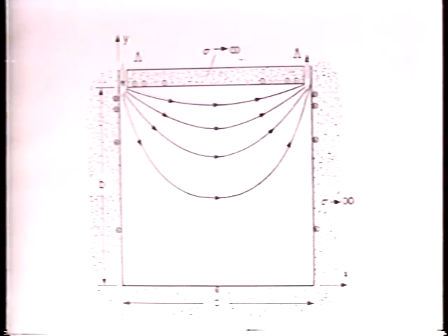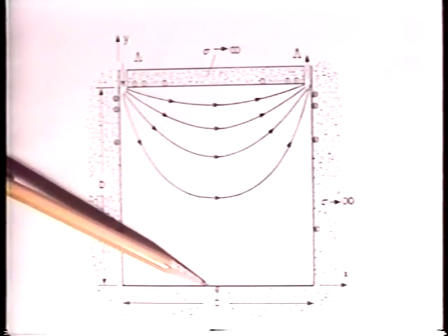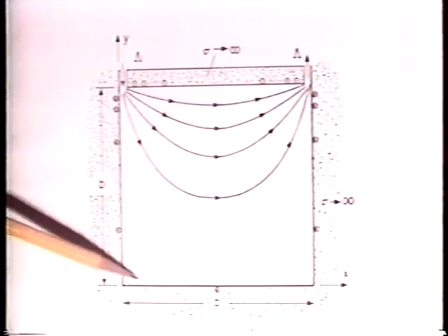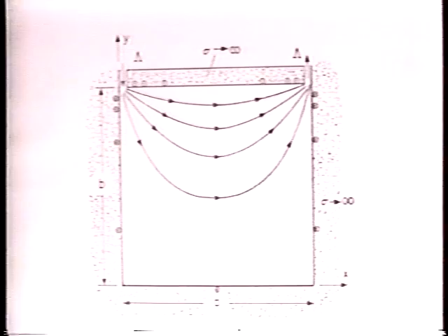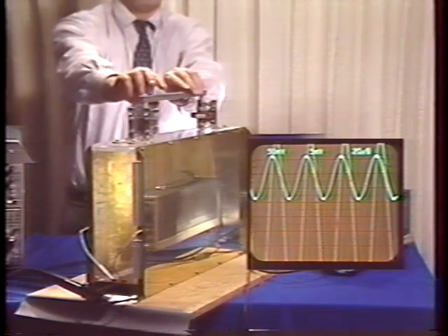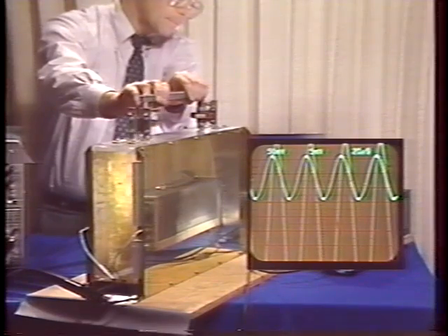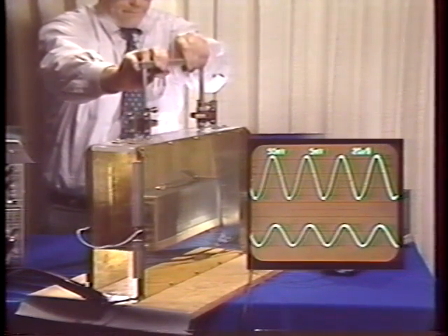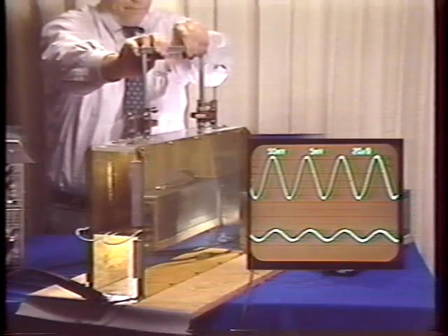The current in the lower electrode is the integral of the tangential magnetic field intensity over its length. By the nature of Laplace's equation, this field intensity becomes weaker as the distance between top and bottom electrodes increases. As the distance between electrodes increases, the fraction of the current that returns in the lower electrode is reduced.